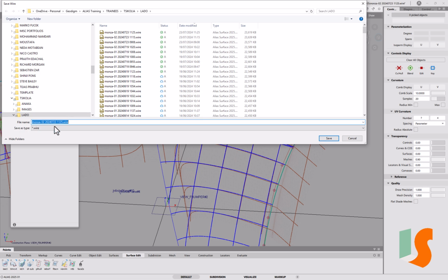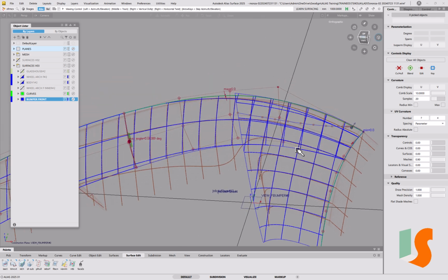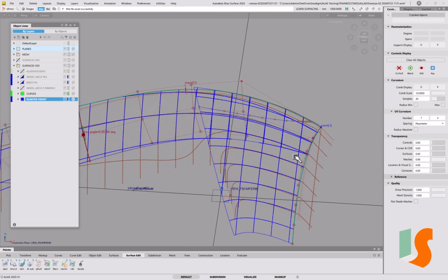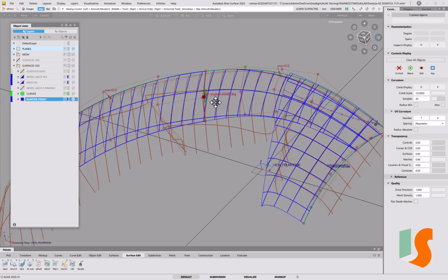I think the time may be coming soon where I need to actually take more control of this. So rather than having it intersect, doing whatever it's doing with two surfaces which are unrelated, my plan is to take this surface, put in the line that we want in terms of the intersect, trim convert it, and then align it in G0 to this underlying block here.